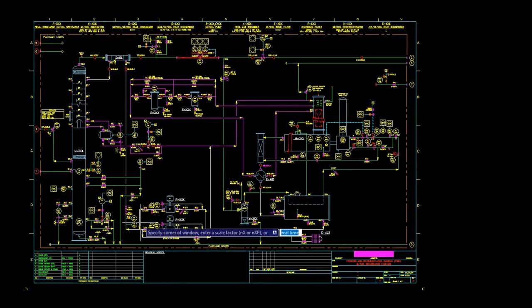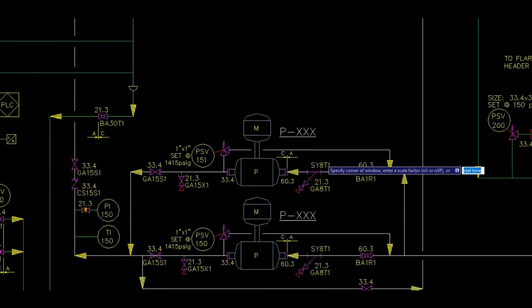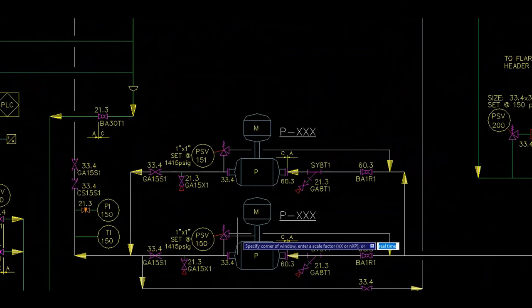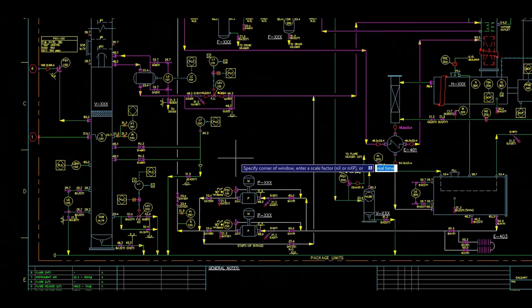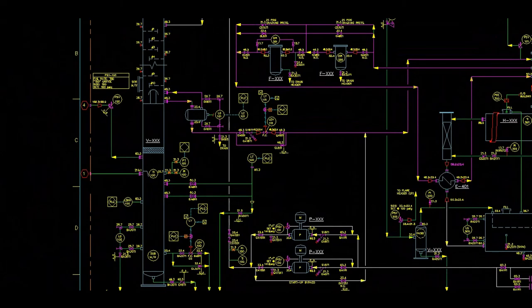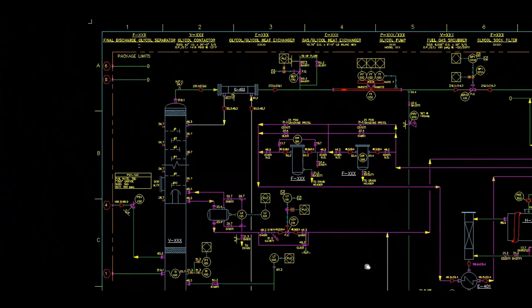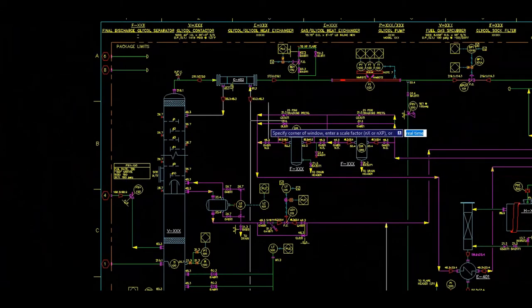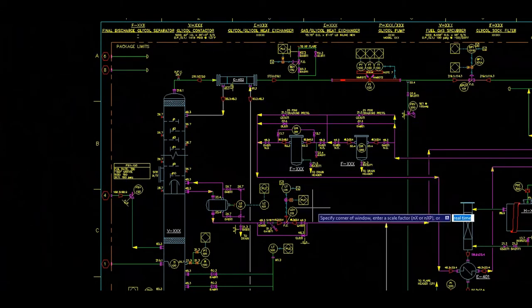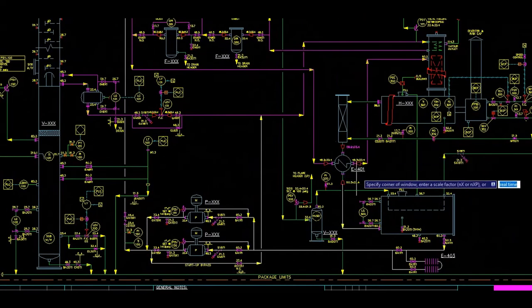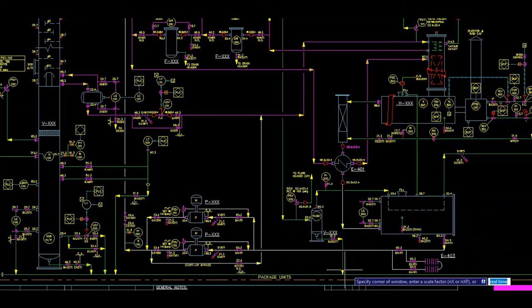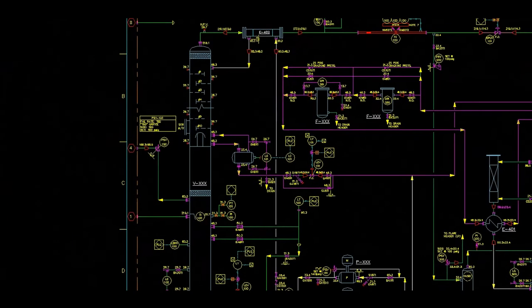And these are inline centrifugal pumps. Their purpose is to boost the lean glycol pressure to the inlet pressure of the contactor and circulate a volume predetermined in the design stage. Other units shown are the gas glycol exchanger, filters, the sock filter and the carbon filter, rich lean glycol exchanger, glycol reservoir, flash tank, air exchanger, and a little vessel here to maintain the glycol level in this section of the contactor.